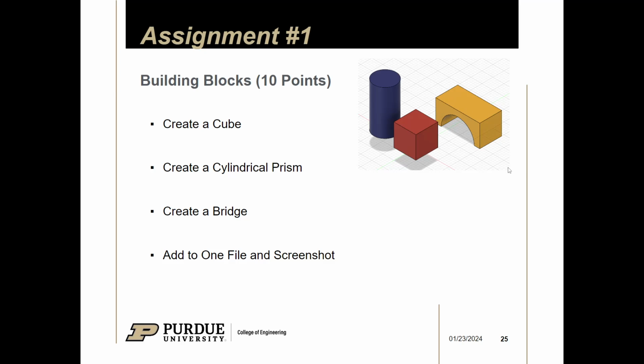So there's a number of ways you could do it, right? You could extrude a big square and then cut out the circular piece, or you can extrude the circular piece and the rectangle at the same time, right? So there's a bunch of ways you can do it. There's no technically wrong way of doing it, but there are more quote unquote efficient ways of CADing, right? So I like to choose a more complex side first. So I have all the information in one sketch, and then I can extrude it, and it's just one operation.